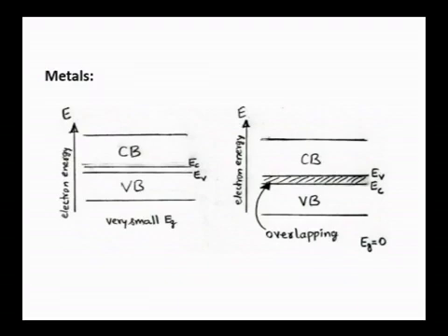Now, based on energy bands, we can distinguish between metals, insulators and semiconductors. Essentially, an energy band comprises closely lying energy levels corresponding to electrons in different states. If they are free electrons, conduction electrons, the energy levels lying close by corresponding to those electrons constitute the conduction band. And the valence band comprises energy levels which lie very close by corresponding to valence electrons. There may be a small gap, marginal gap or large gap, depending on the material, between conduction band and valence band. This we call the energy gap.